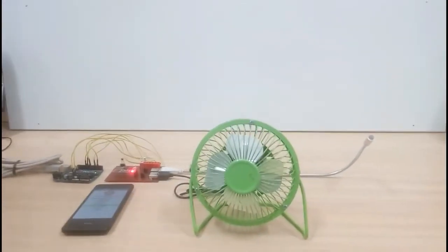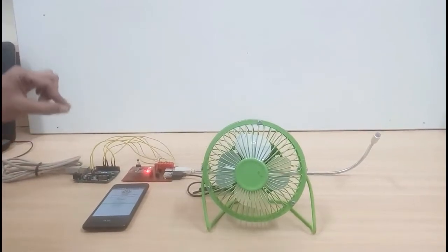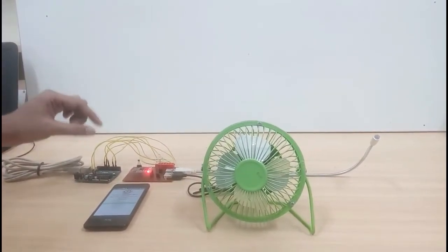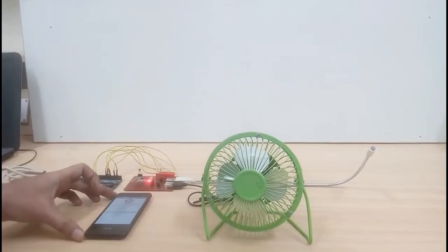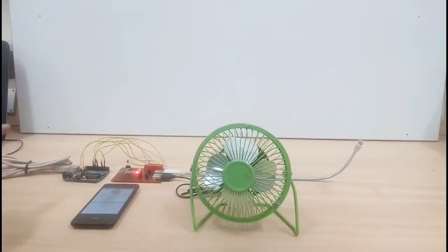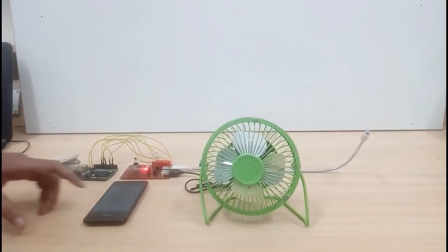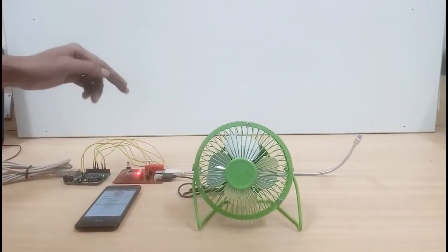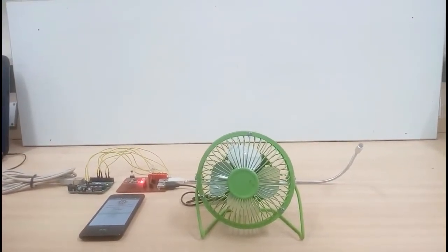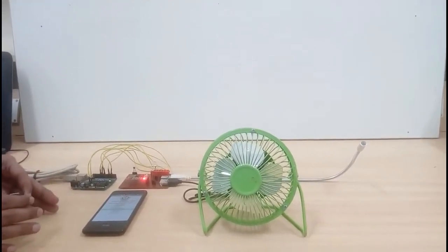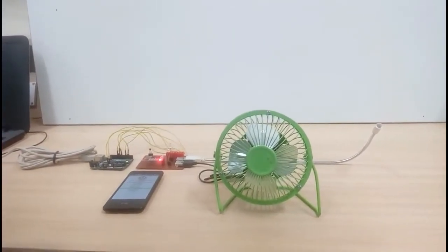How the system works is that when I move a magnet in the vicinity of the Hall effect sensor, it generates a signal which goes to the Arduino board. On receiving this signal, the Arduino board issues a command which goes to the Android app via the HC05 Bluetooth module. On receiving this command, the Android app launches the speech recognizer, and now the subject can speak his command into the app. This command is then converted into text, and this text is sent back to the Arduino program via the HC05 module. Here the Arduino program ascertains what command has been received and then takes the corresponding action. We should have a small demonstration.